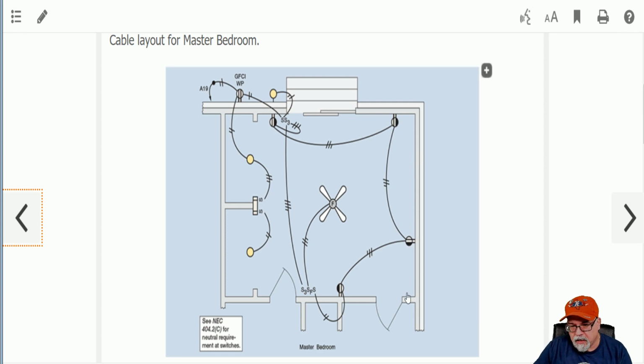Okay. Now, can I put it less than 12 feet? Absolutely. If you want to put one every 5 feet, 6 feet, 7 feet, whatever you want, that's your design. But if I go the maximum 12 feet, then any point on this wall would be within 6 feet of a receptacle. Now, we have to keep in mind when we're designing this, because let's look at this wall real quick. What if I moved this one right here? It might be this one within 6 feet.